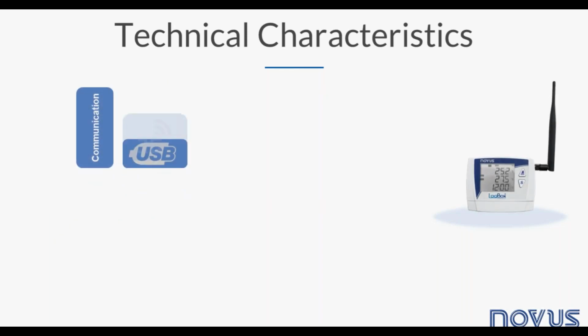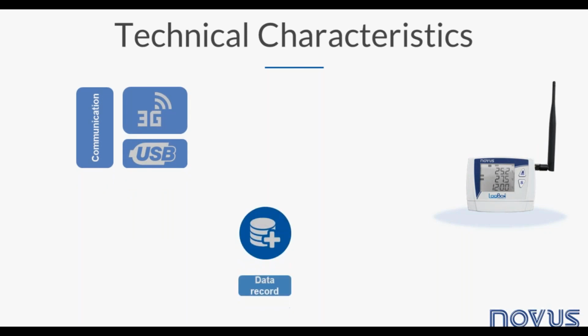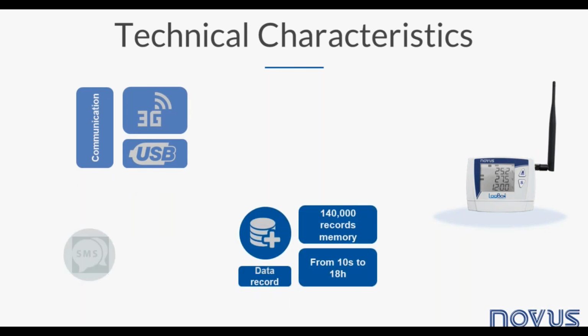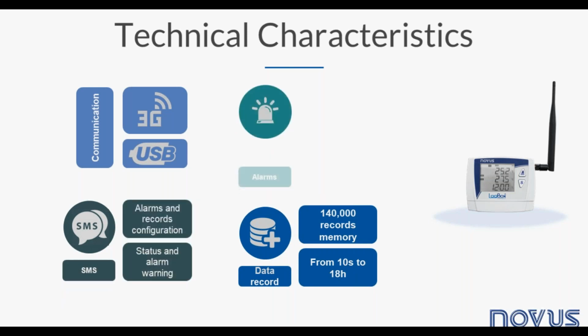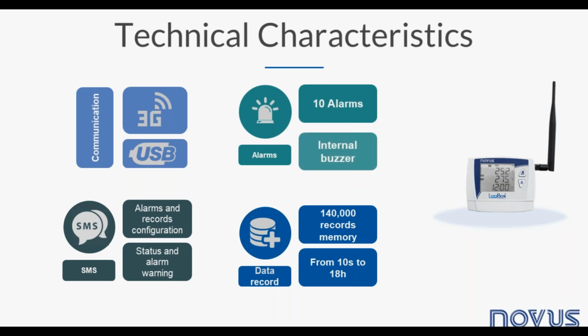Lockbox communicates via 3G or 2G cellular network. Depending on the strength of signal, it clamps automatically into the strongest 3G or 2G radio base station. It keeps monitoring the network. When the signal condition changes, it changes to the strongest one. Both configuration of parameters and data download can be done through the cellular network, but it has a USB port for on-the-bench or on-site configuration to facilitate commissioning.